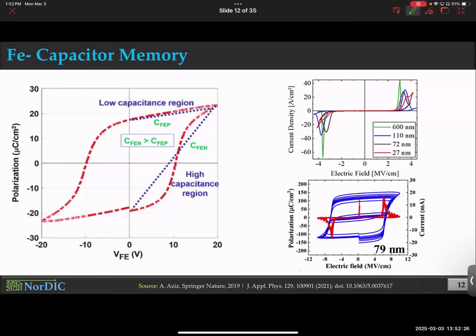So when you read, you apply a certain voltage. Okay. Let's consider two scenarios. You either had this positive polarization stored or negative polarization stored. Okay. And I'm going to apply a voltage of this much, like maybe 25 volts or something. I know the numbers are crazy, but just bear with me for a second. Okay. This is what we could possibly do. So if you were storing this positive polarization, then with this voltage, which path will you follow? The top one or the bottom one? The top one, because you are already in the positive polarization region, right? So you will go through this route.